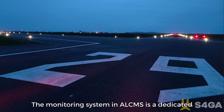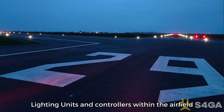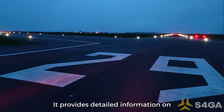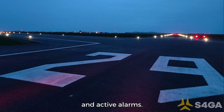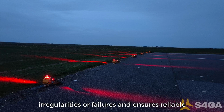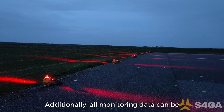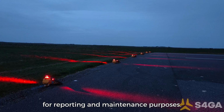The monitoring system in ALCMS is a dedicated feature that allows real-time supervision of all lighting units and controllers within the airfield network. It provides detailed information on device status, battery levels, operating modes, and active alarms. The system helps operators quickly detect irregularities or failures and ensures reliable airfield operation. Additionally, all monitoring data can be logged or sent automatically via email for reporting and maintenance purposes.